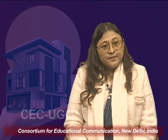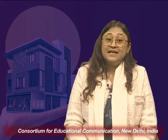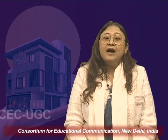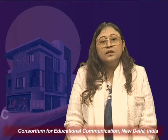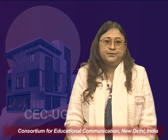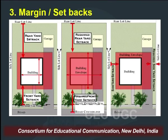Third important aspect is margins or the setbacks. As discussed in the previous lecture, there are three aspects of the margins or the setbacks. First is the front, second is the rear, and third is the side. So, the open spaces inside and around the building, particularly residential, have to cater to all these three aspects because of basic lighting and ventilation requirement and overall safety of the occupants of that home.